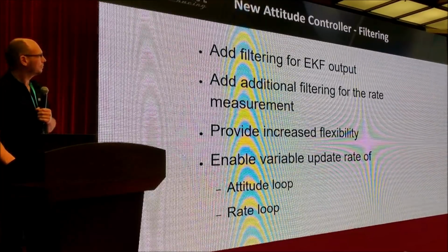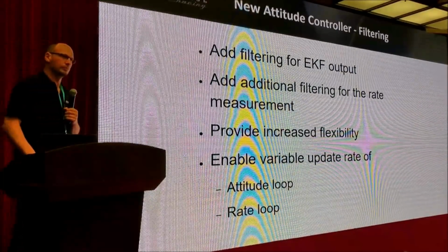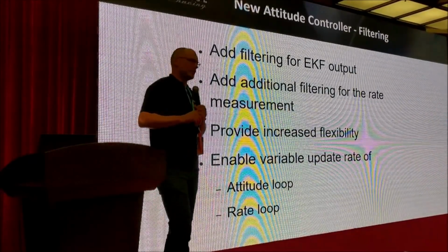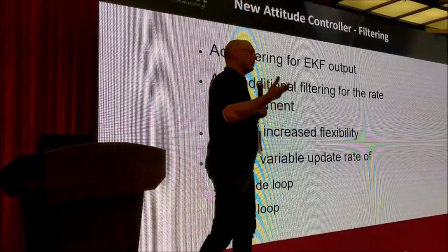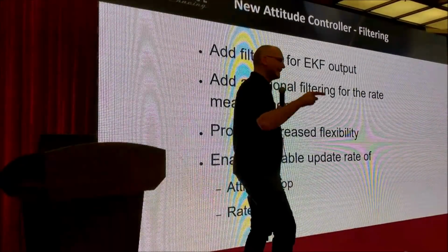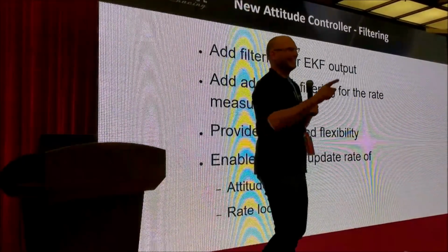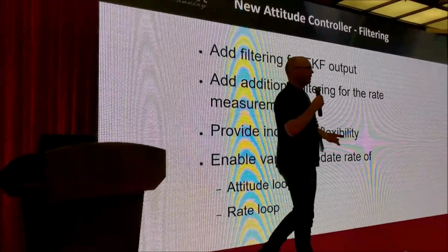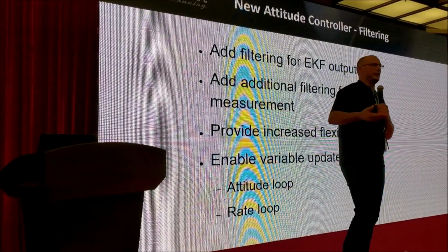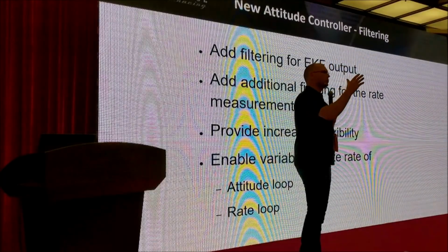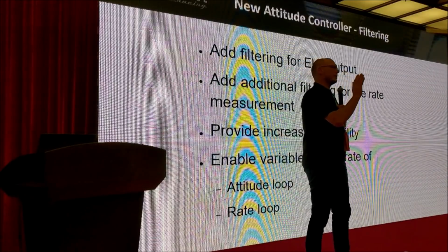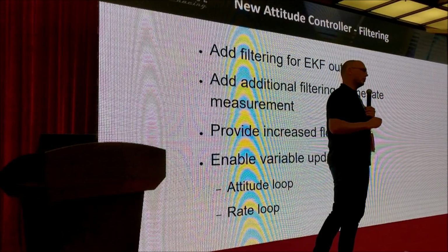How do you know what that frequency is to a notch? Okay. Is that flexible? Yes. So the way we do this, who knows what an FFT is? Yeah. By recording the sensor data, we can do an FFT, which shows the spectrum of your signal. And that tells us where you're seeing your noise.